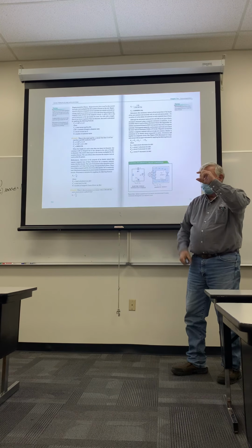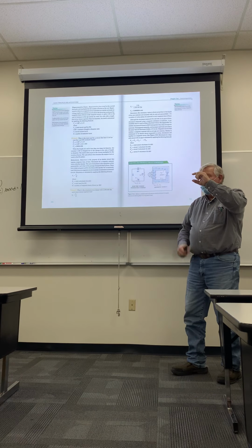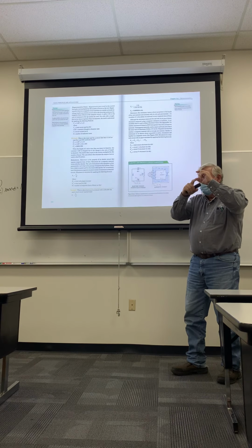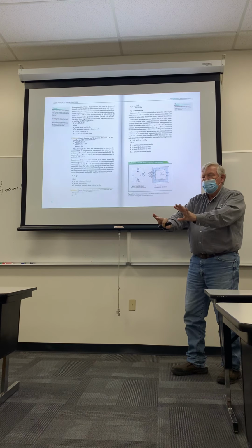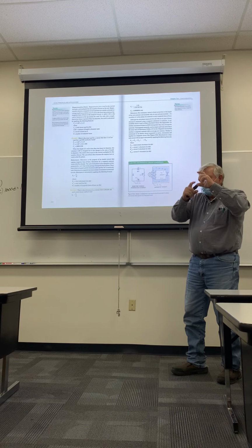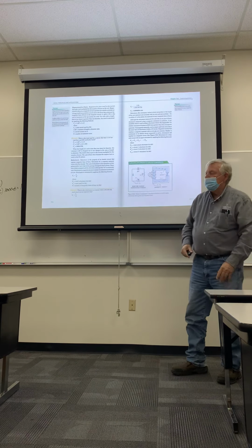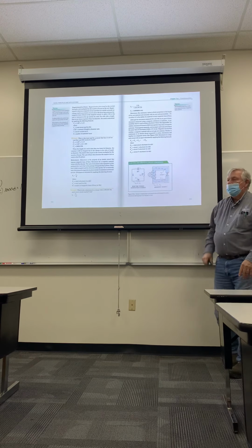What happens, there's an air gap. And because there's an air gap, and there's a high voltage that's pushing that through one side, the cathode, then it jumps across through the air. Air has a lot of resistance to that flow. But it'll jump across, and that little spark that goes across here is what ignites the gas. So that can become very useful.